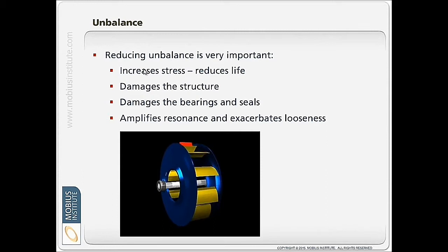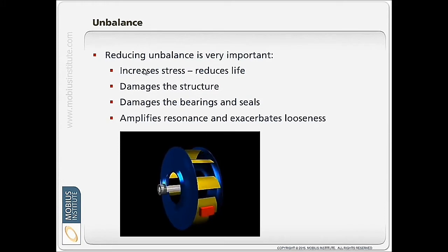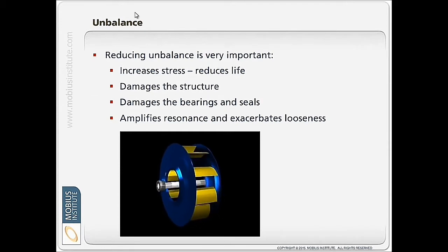And if there is any resonance occurring, then the more unbalance vibration, we get more amplification and therefore much higher vibration. Same if we have any looseness, then that unbalance drives the ability for it to be loose, if you know what I mean. If it's loose, then we get more motion if there's more unbalance vibration.